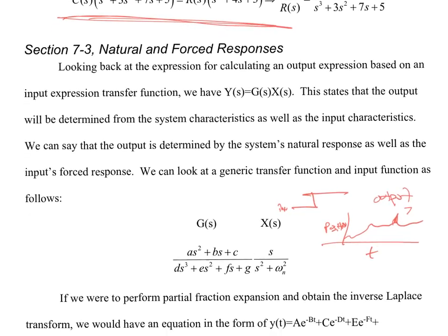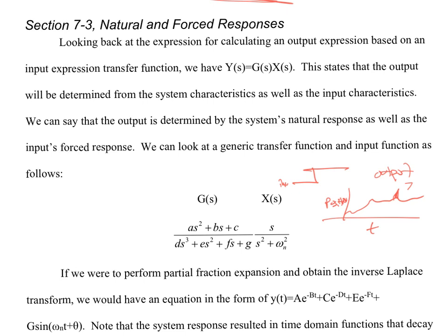So I've actually only seen the results of it done once. The only time I've ever been involved in modeling a process that was not an electrical system is I worked at a nuclear power plant in New Jersey. Actually, it was in Delaware, but it was the only way you could get to it was New Jersey unless you swam or took a boat. But the idea was this plant had what's called a moisture separator reheater, and I had to design a control system that would control the heating up of the temperature, so opening valves and making sure that the temperature didn't go too high.